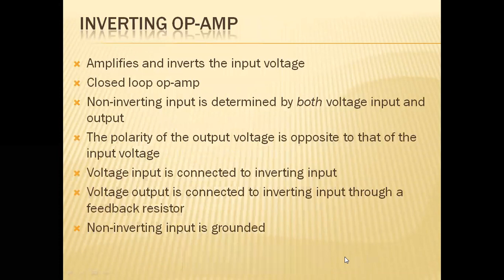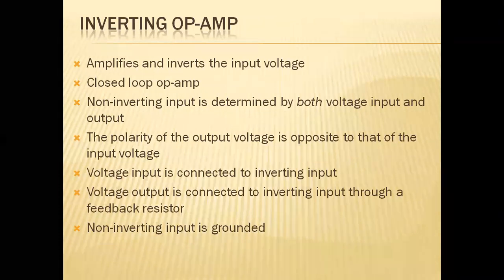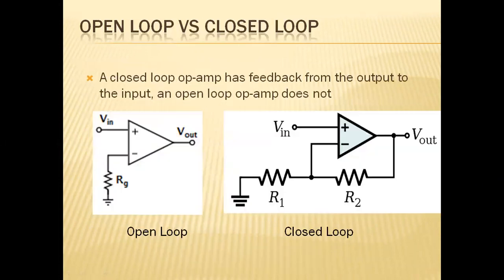Right? In the case of the inverting operational amplifier, the negative polarities are connected to the circuit. We'll verify with the diagram. In the inverting case, the voltage input is given to the negative terminal, so the polarities are interchanged. The voltage input is connected to the negative, and the ground is connected to the positive. The remaining circuit is almost entirely similar.